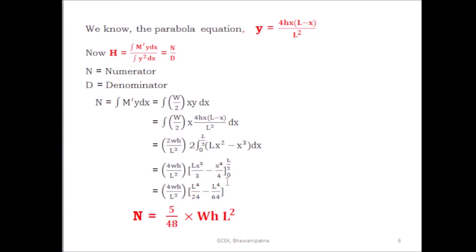After simplifying, the numerator is 5/48 WhL². So the integral of M'y dx, the numerator, is 5/48 WhL². Then find the denominator, which is the integral of y² dx.